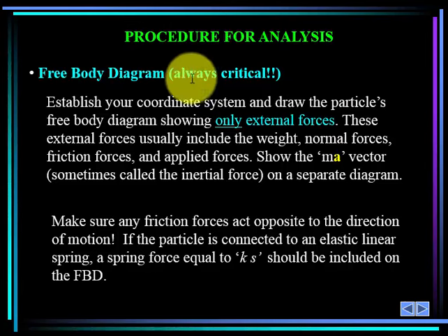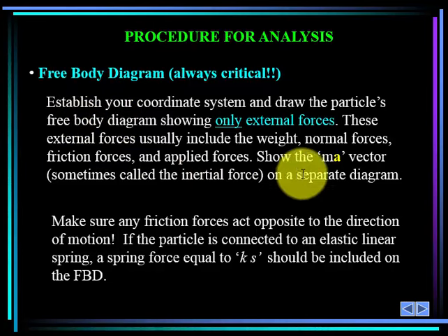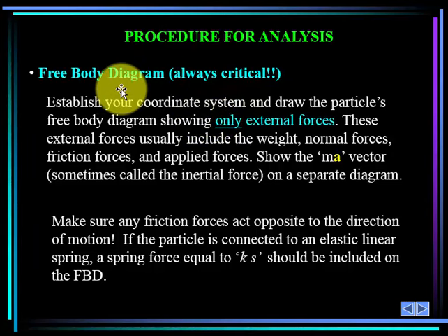Our procedure, and this is critical, is that you always draw a free body diagram. I will say again, I've worked lots and lots of dynamics problems. If I don't draw a high quality free body diagram, I've got about a 50-50 chance of getting the problem right. And I suspect the same ought to be true for you as well, that you won't get the problem right many times if you don't draw the free body diagram. So on that free body diagram, we will establish a coordinate system, and drawing the coordinate system and in particular showing the directions of the positive coordinates is important.